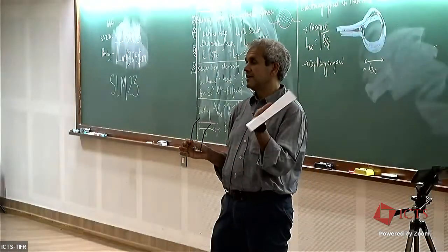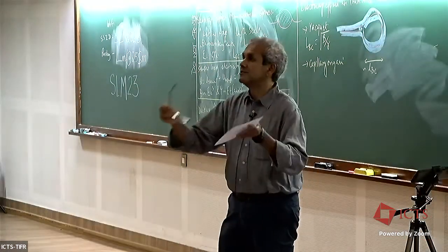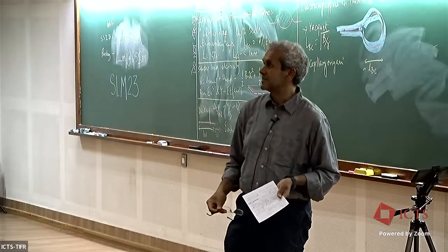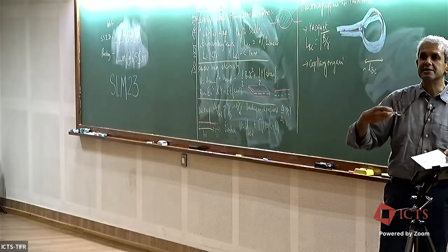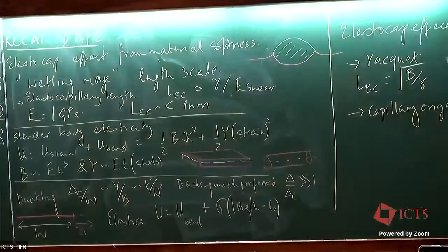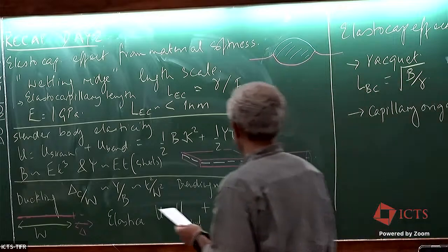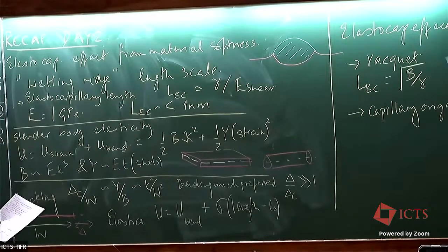If you try rolling a droplet on it, there's a huge drag from the substrate impeding the motion of the droplet, which normally, droplet motion speeds are set by the viscous term, which is always just the liquid itself, okay? It also suppresses splashing, it suppresses spreading. So there's a number of ways in which this can show up. And then you can start engineering the surface to make the drop go here or the drop go there, depending on the substrate stiffness. That's the first thing we talked about.